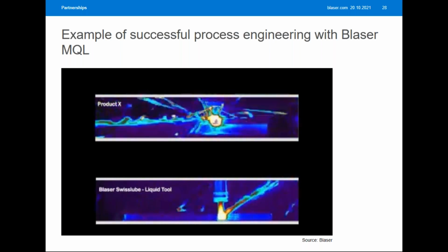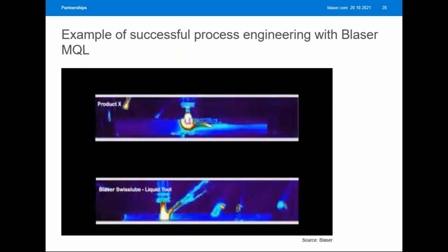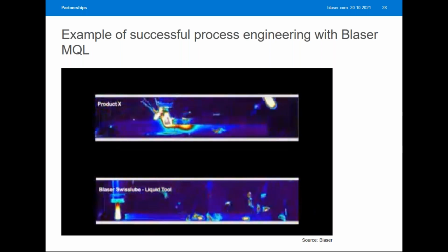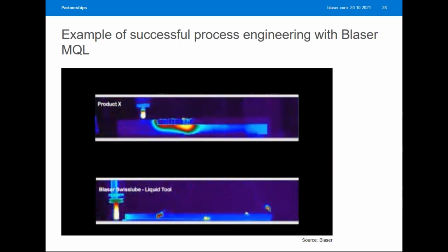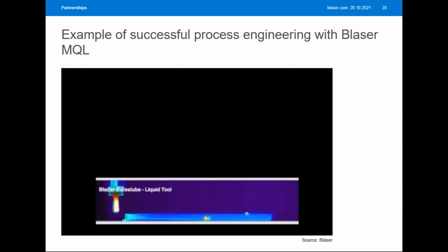You see that now in the top row. So there really wasn't any tool life at all. And with the higher parameters, we didn't have any tool break, and we were able to just mill the material down.